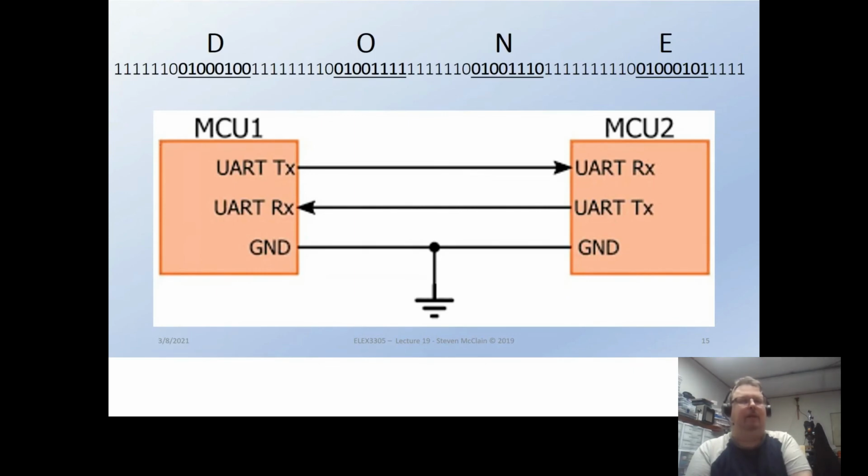If you're actually connected to the back of an old school RS-232 port, these voltages could be as much as plus and minus 25. Oh, yeah. You have plus and minus 25 up to your MSP432. Kaboom.